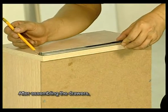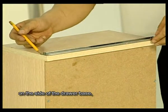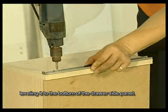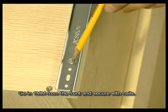After assembling the drawers, we should install one part of the ball slide on the side of the drawer base, leveling it to the bottom of the drawer side panel. Go in 1 mm from the front and secure with nails.